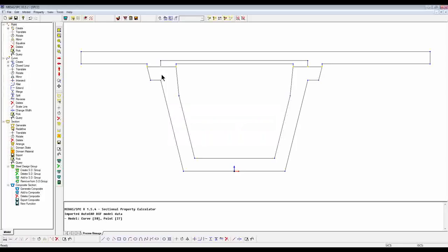So if you're having any difficulty importing something and encounter any issue, pay attention to your unit setting when you open the Section Property Calculator tool, and also the tolerance, and also exploding them back in the CAD program. And also over here, make sure that you disconnect them at the intersection and also erase duplicate members just by saying OK to the initial question the program asks you.